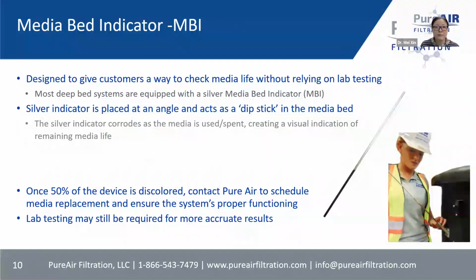So besides this media life analysis in the lab, by analyzing the chemical activity, we also provide a media bed indicator, which is designed to give customers a way to check media life without relying only on lab testing. Most deep bed systems are equipped with a silver media bed indicator, and you can put the indicator at an angle into your bed system, where it acts as a dipstick in the media bed.